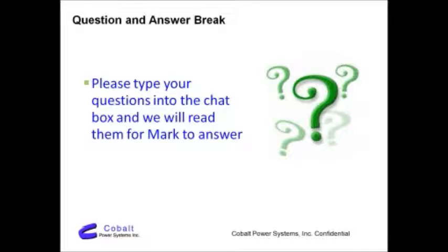Right, so a good quality solar panel, like a SunPower, will have a 25-year power output warranty. That means the manufacturer is warranting to you that the solar panel will produce typically 80% of its rated power at the end of year 25 and 90% at the end of year 10. When we do a proposal to a customer, though, that degradation is in the numbers already. It's basically 1% a year. It's pretty darn good. How about microinverters?